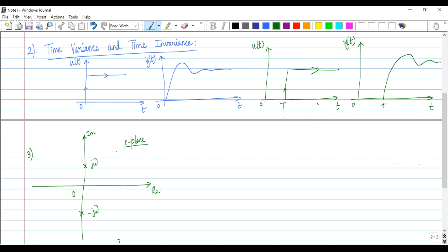Now if I have a transfer function where all the other poles are in the left half plane and there is only one pair of non-repeating poles on the imaginary axis, the moment we provide an input of the form cos omega t or sin omega t, the output is going to be unbounded in magnitude. So that's what we essentially looked at.